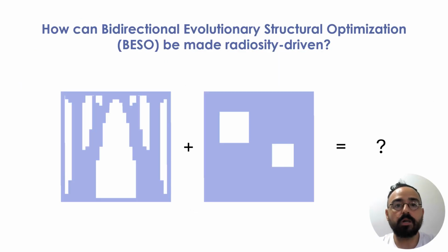When we are looking at the principles of structural optimization and daylight analysis, a natural question arises. Can structural topology optimization and daylight optimization be fused into a single framework? And how? The answer is yes. Despite sharing entirely different physics, they share a fundamental common desire, the removal of material. Structure removes mass to find load paths, while daylight removes mass to create apertures. If they both were seeking to generate voids within a shared design domain, a true fusion would be mathematically viable.